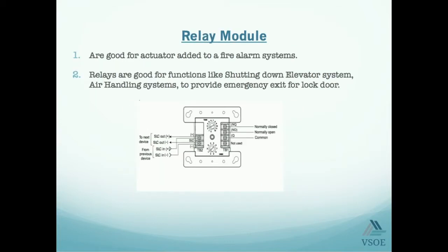A relay module is a module that are good for actuator that is added to a fire alarm system. A relay modules are a good module for functions like shutting down elevator system, air handling system, and to provide emergency exit for locked doors.